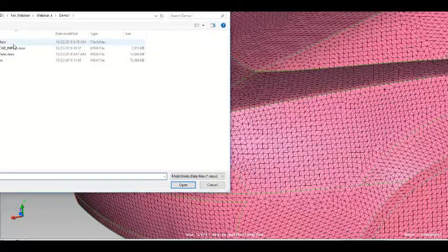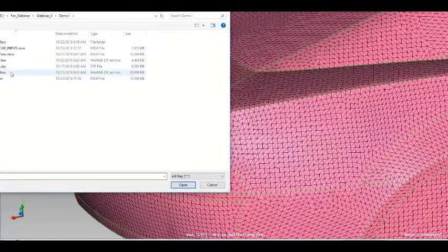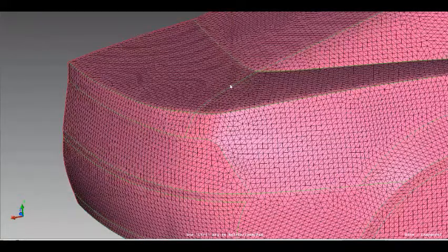someone else also asked us about that methodology, but when you look at a fillet in this particular region, you have a uniform fillet. When you have a fillet that's converging to a smaller size or something like that, then that's not going to help you out any. So this is why we implemented the percentage change approach, because truly in the CAD domain, your fillets are going to change drastically. They're going to converge in certain regions. They're going to form into different fillets in certain regions. So it needs to be based off a percentage. The radius may not be uniform throughout the fillet. That's why percentage is. Oh, okay, I see the point.